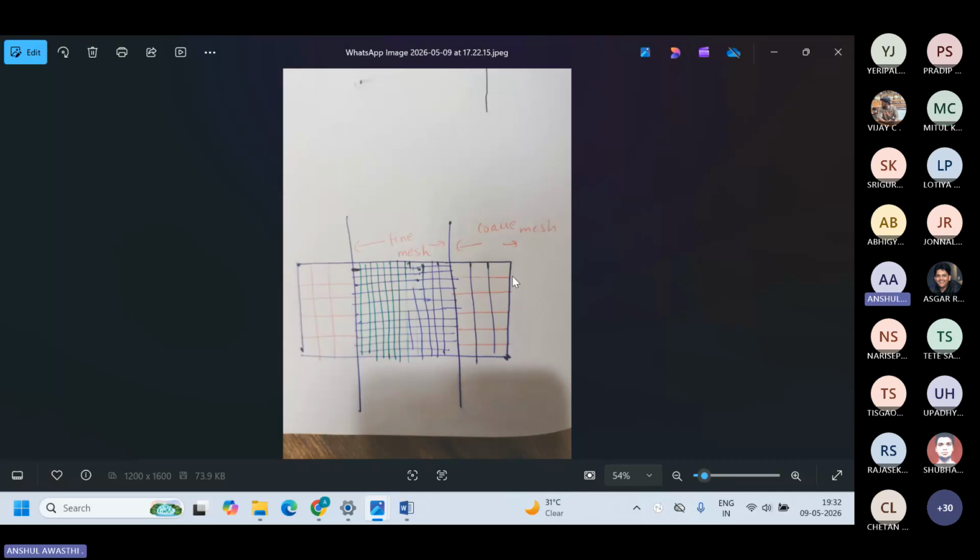Yes, sir. If you're making the size of mesh 10 nanometers, then the total number of rectangles will be 50. If you are making the size of your mesh 1 nanometer, then the total number of rectangles will be 500. So it is just the way you are breaking your device into small blocks. The finer the blocks, the more accurate the result.